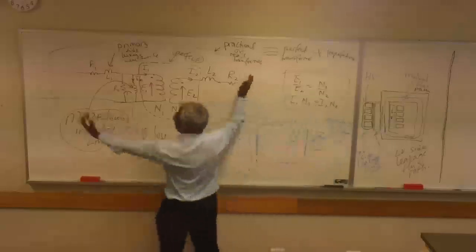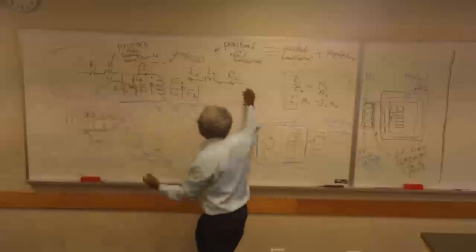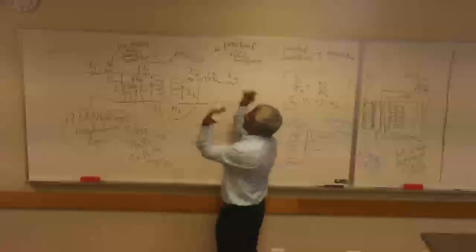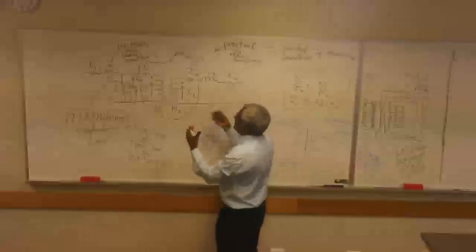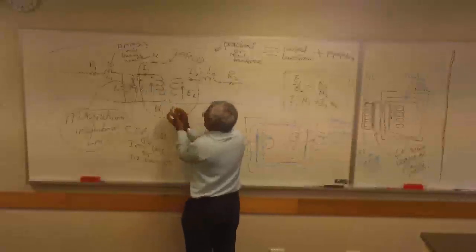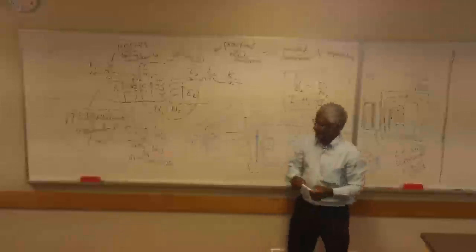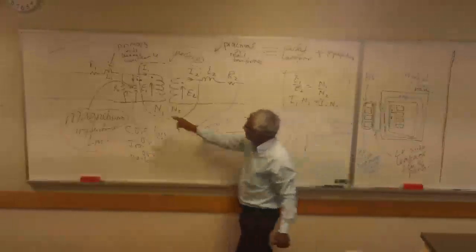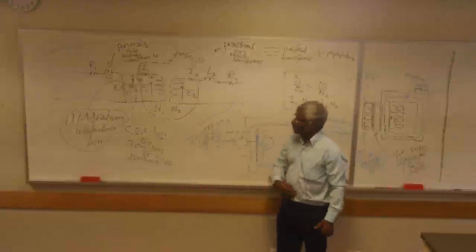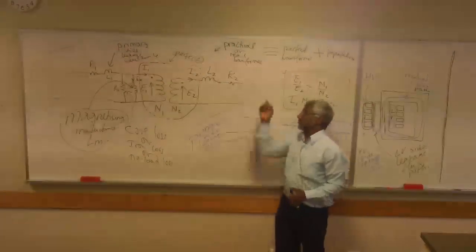So the transformer, the outer thing, has these terminals of the transformer. In practice, we can't get in there, but we can picture what's in there. We imagine something perfect, plus the four imperfections that we have covered today. This one is in parallel. The magnetizing current is in parallel because it is proportional to the voltage that you apply. It's not proportional to the current going through the winding.